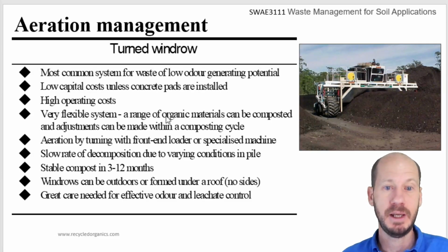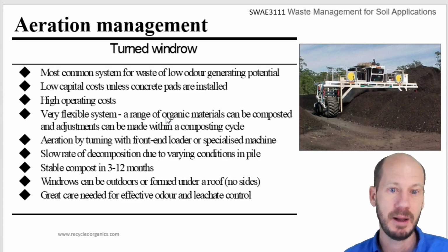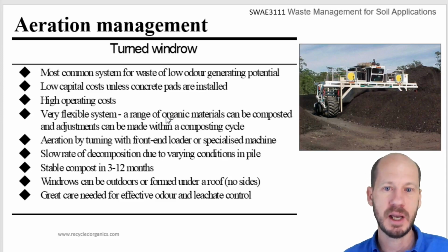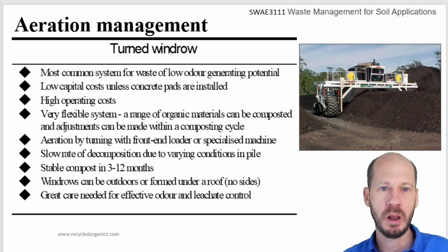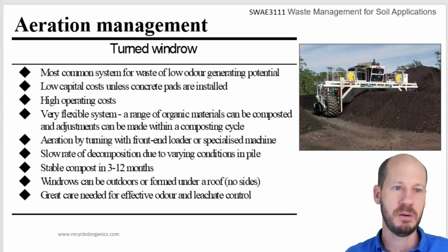Management of the aeration in the composting process. It's very important that you have oxic conditions. You cannot really let the carbon dioxide build up too much in the compost pile. Otherwise, the anoxic conditions will decrease the speed of the decomposition of the material, and also will cause this anaerobic process that will release bad smells, bad odors.